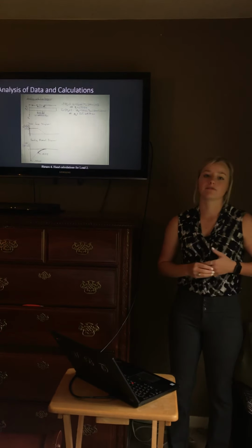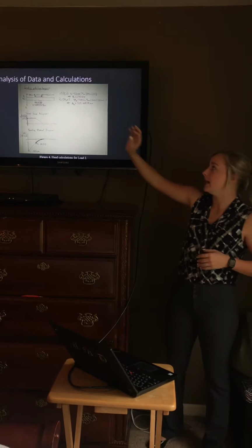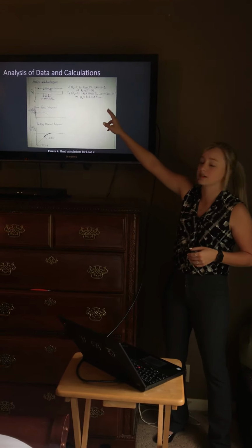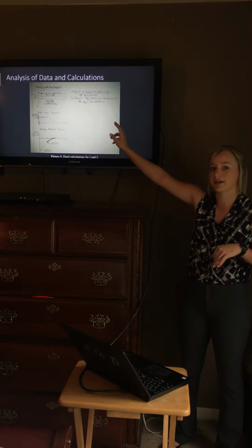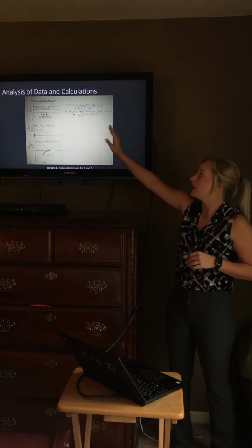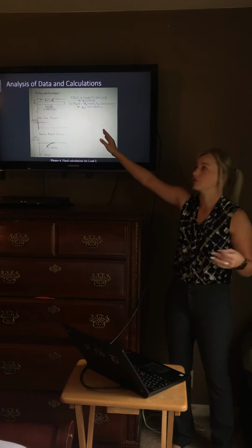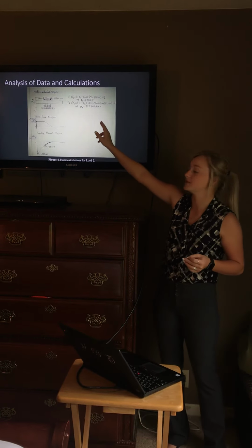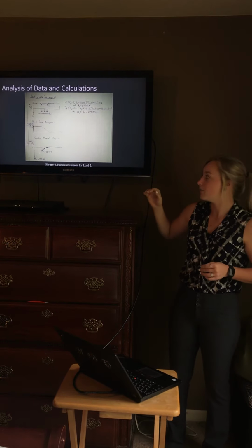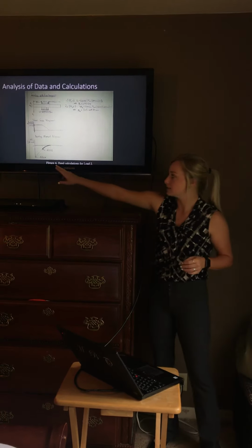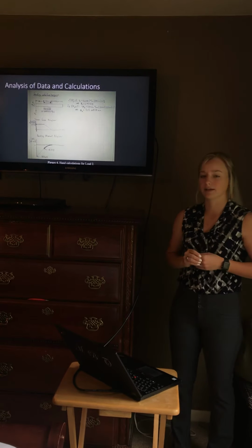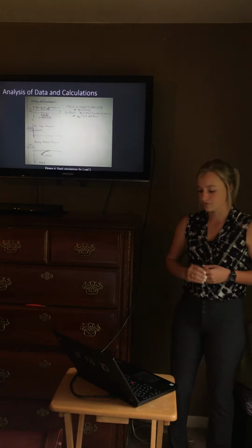The same thing was done for the loading with 5 hangers. As you can see, the reaction forces did increase, so we have 1.4712 newtons in the y direction now, whereas before it was 1.1772. And then the reaction moment also increased as well, with 323.664 Newton millimeters. The diagrams were drawn the same way. You can see our maximum bending moment is still all the way at the left-hand side, and that was 323.